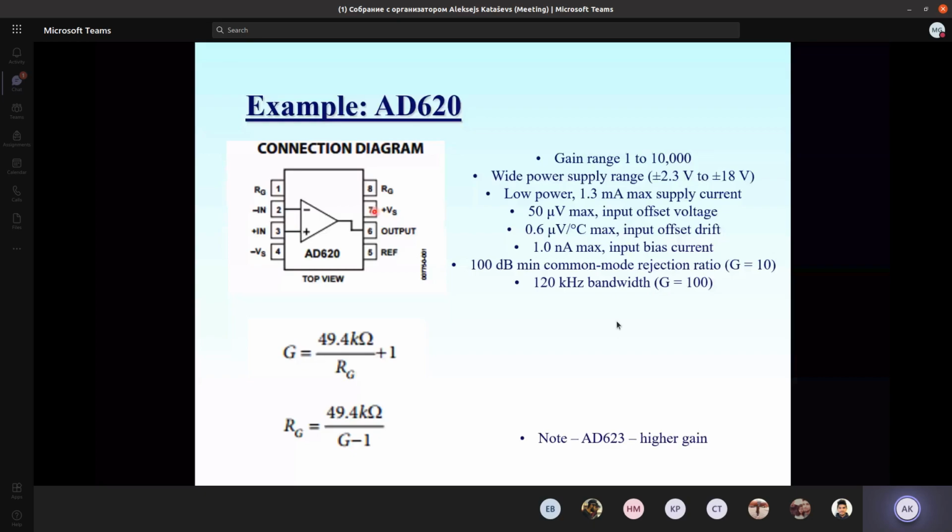to feed the amplifier. So we have the inverting and non-inverting inputs, V1 and V2, and an output, which is absolutely clear. And we have two more pins where we attach a resistor, between RG and RG, the first and eighth legs of the package, and this RG controls the gain of the amplifier.